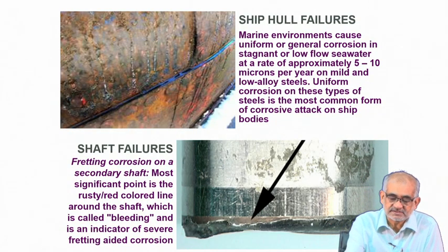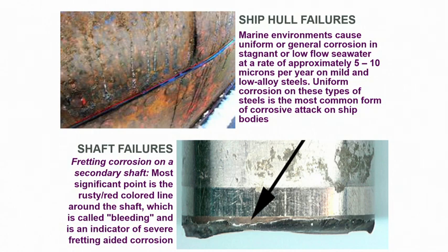So this is what we were discussing, that in the ship hull, this is the joint essentially. These are basically plates which are riveted, which are joined mechanically. So we certainly expect that corrosion can occur around these rivets, which may be compositionally different. And there's no necessity all the time to have pure copper and iron. We may have copper-based or iron-based alloys, which in the electrochemical series may form a galvanic couple by being one electropositive, the other electronegative, or cathodic and anodic.